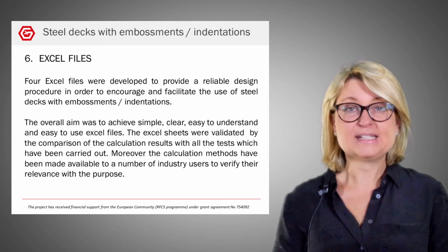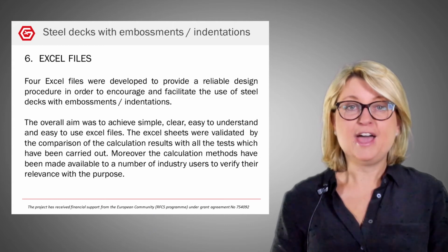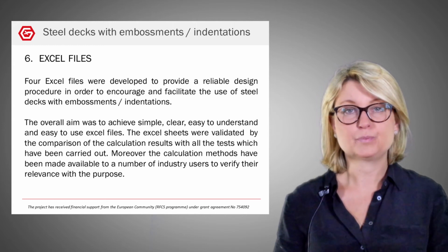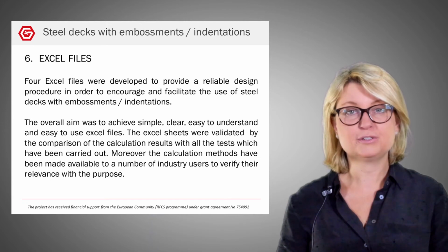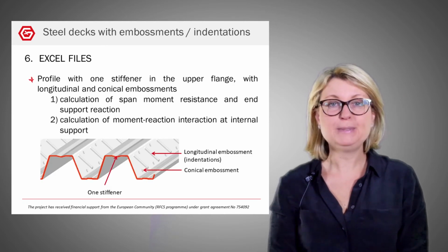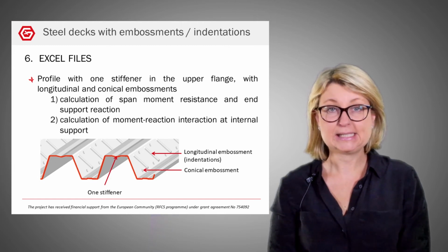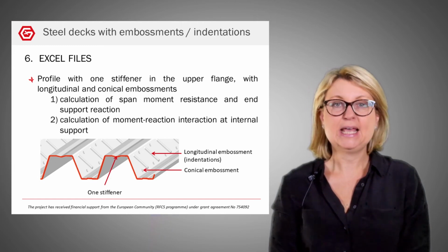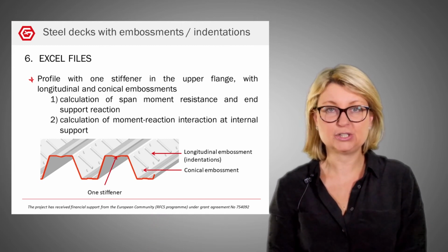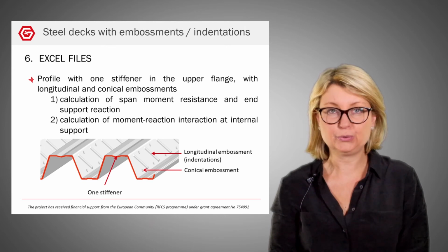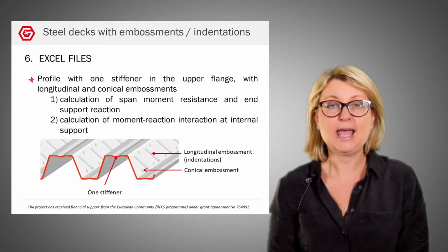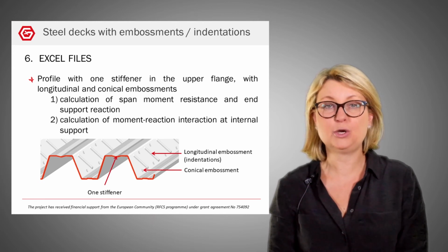Moreover, these calculation methods have been made available to a number of industry users to check their relevance with the purpose. Thanks to these tools, you will be able to calculate span moment resistance and support reaction and moment reaction interaction at the internal support for a profile with embossments and indentations, and one stiffener in the upper flange.